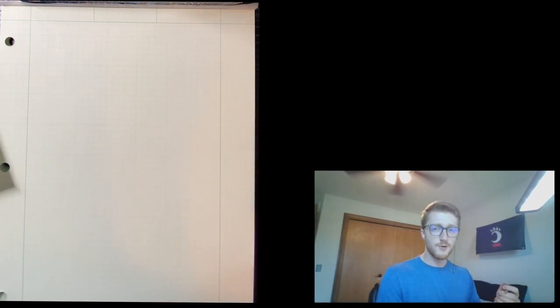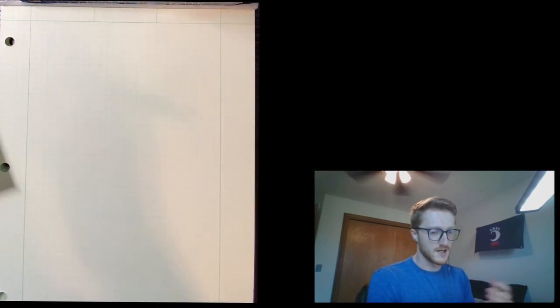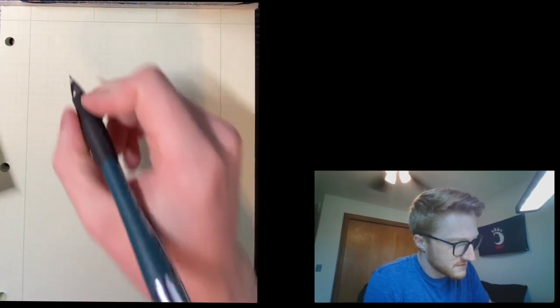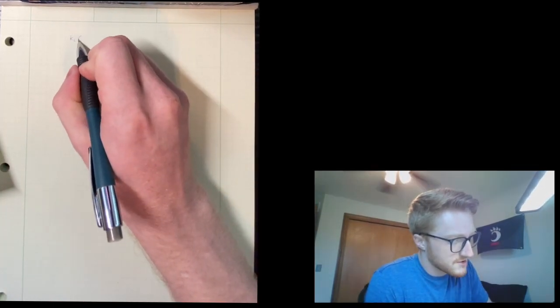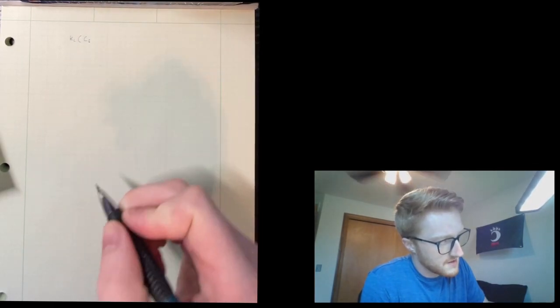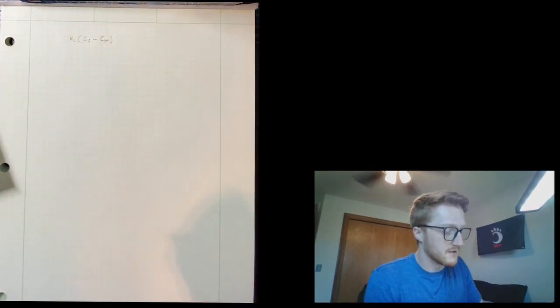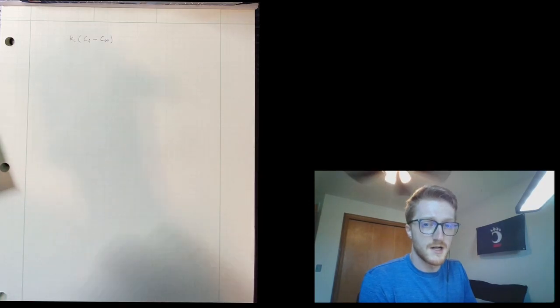And so I want to write out the energy balance relation between these two, relating the mass transfer to the heat flux from the air to the wet surface. The way we can write this is we have a mass transfer. So you have a mass transfer coefficient, and then you have a concentration difference from the surface. So you have more water at the surface compared to the concentration of the air, and so you have a mass transfer between the two. And you're going to need to supply heat for this to happen.